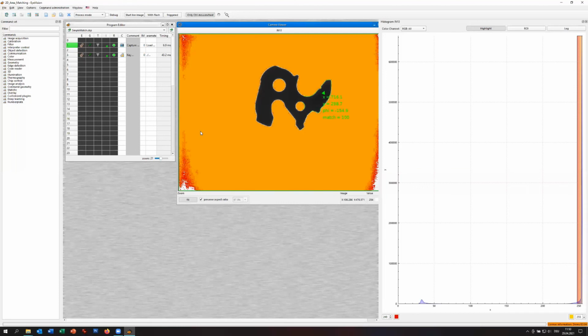You can also do it with FPGA pre-processing. If you remember, for the smart line scan camera, we had this Zynq CPU with an FPGA on board, which can do this homogenization through the line. So if you have a line scan camera with these artifacts from the lens, you could correct these for each incoming line, and you wouldn't see it in the field of view. And it's in the pre-processing phase, before the image is in your processing, in your operation.